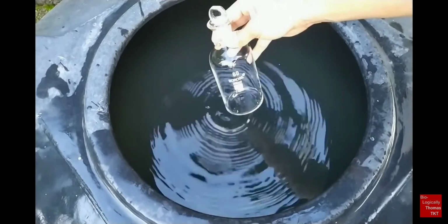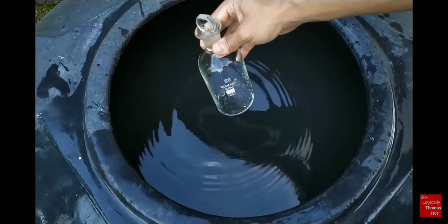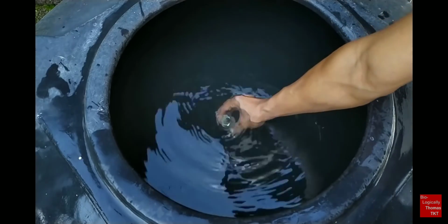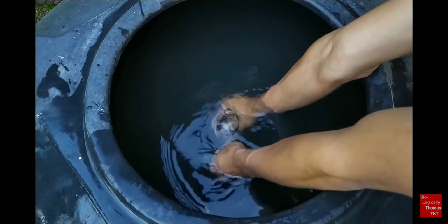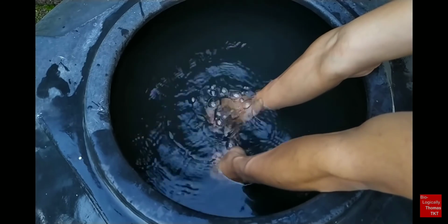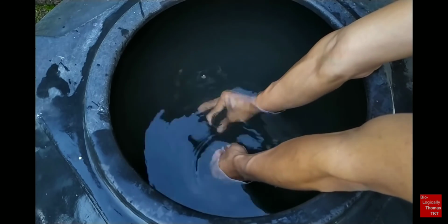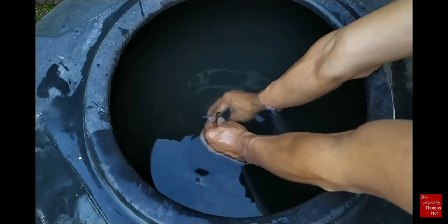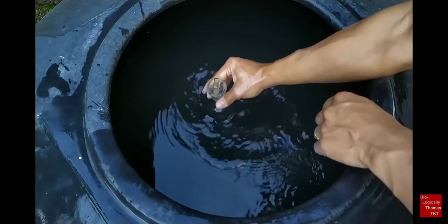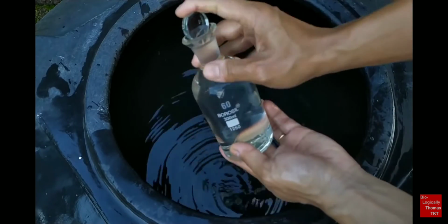To collect the water sample, take a BOD bottle with intact stopper and immerse it to the desired depth in the water source. Now carefully remove the glass stopper from the bottle and allow the water to seep into the bottle. Close the bottle once it's completely filled with the water. Make sure no air bubbles are trapped in the bottle.